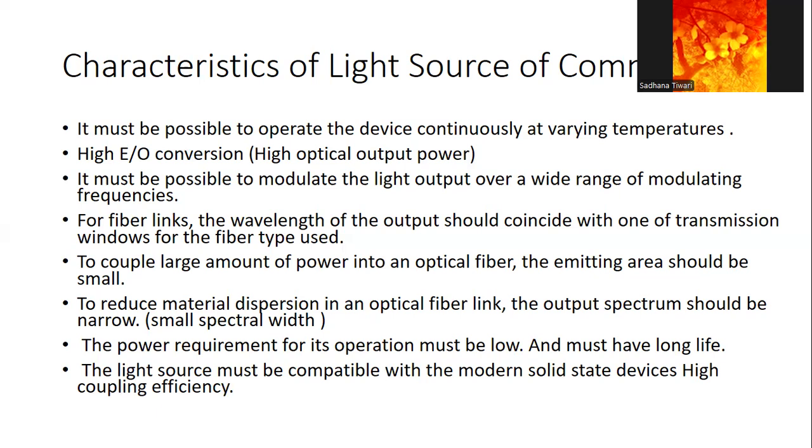Again, we have to keep in mind the power requirement of the source and its reliability, its lifetime. Its required power must be low. So we select our light source in such a way that it has a long life and the power requirement is low. And the last thing is that the light source must be compatible with modern solid state devices like semiconductor and other electronic devices, and it must have high coupling efficiency. So these are the few basic characteristics that must be possessed by any light source that we are going to use in optical fiber communication.